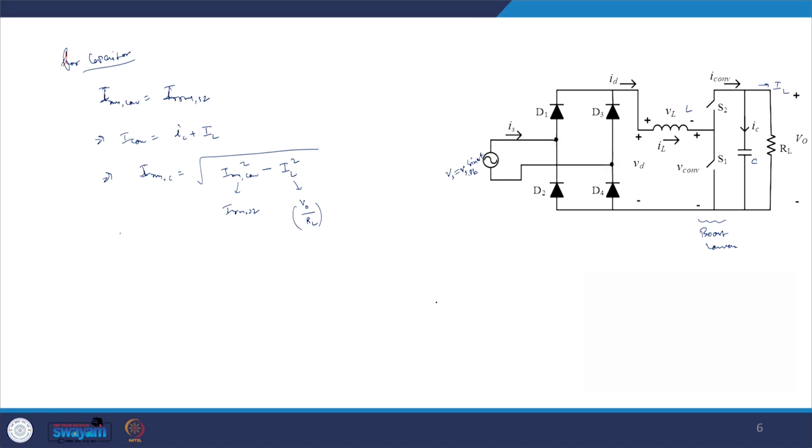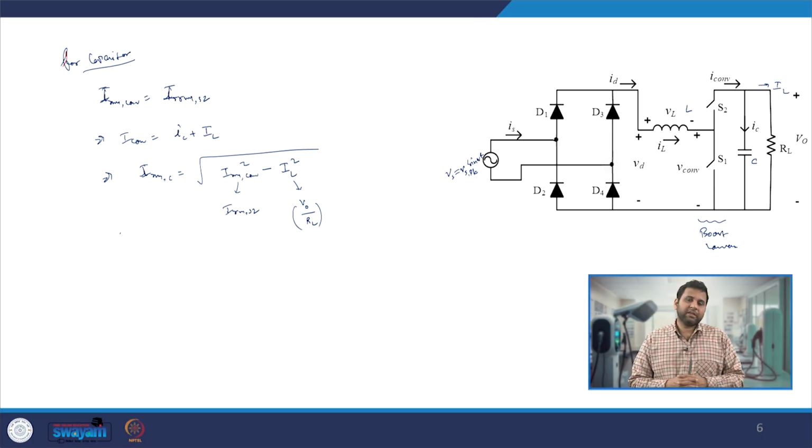Using this information one can select the required components and build this kind of power converter for the required specification, which includes information like output voltage, input voltage, output power, permissible voltage ripple, and the AC frequency. Following this procedure one can easily size the components accordingly, and thus build the single phase boost PFC converter.